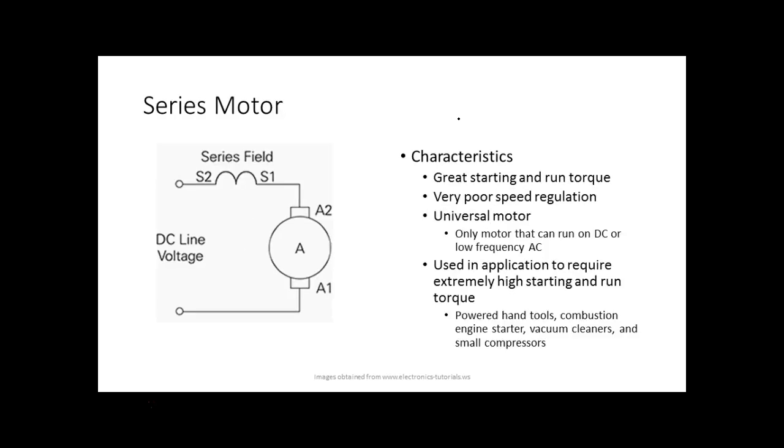Now this is a series motor. What's the advantage of a series motor? Very slow speed, but great torque. These guys give us a lot of torque. We compared this with a hand drill, right? Most of your hand drills are series motors. So we said you hold them up in the air, and they run real fast. As soon as you put them in that piece of wood, what do they do? They slow down. But what happens is their torque's going up, right?